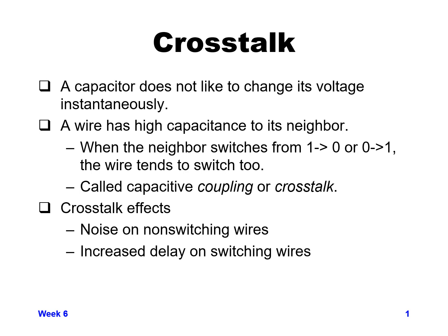Or if you cause noise on your clock wires, it could make the clock appear like it's switching when it's not supposed to switch, and cause a latch or a flop to toggle and capture new data when it wasn't supposed to capture new data. So that can be very, very bad effects.